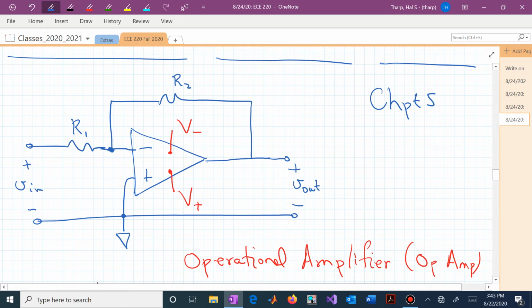It now allows us to operate on signals, and in particular we will learn the relationship between the output voltage and the input voltage, and in this particular interconnected circuit, that's simply a ratio of those two externally connected resistors around that operational amplifier. It's going into the inverting terminal, and that actually produces this inverter or minus sign in addition to the gain, which is a ratio of R sub 2 over R sub 1.